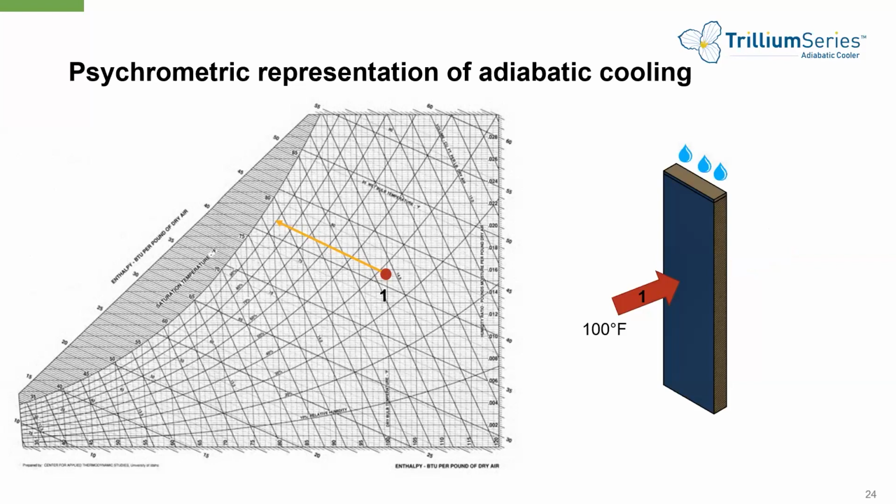The definition of adiabatic is total enthalpy is conserved. So everything that the air gives up in terms of sensible, it is gaining an equal amount of energy in terms of latent. And if we had a 100% ideal cooler, we would be able to cool the air all the way to the saturation line or 78 wet bulb. Of course, no such mechanical equipment exists.